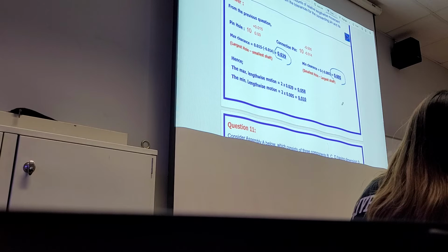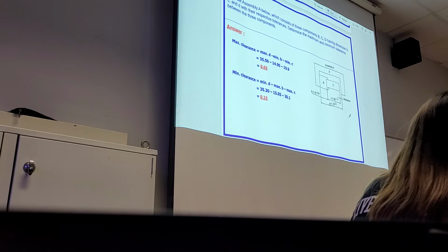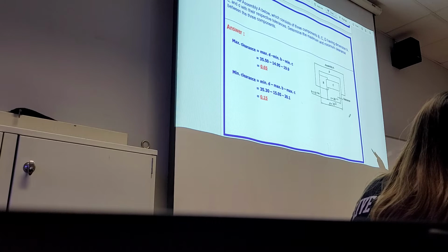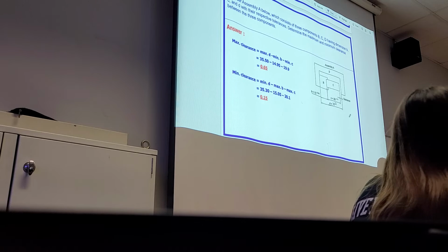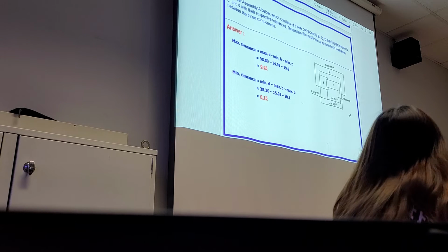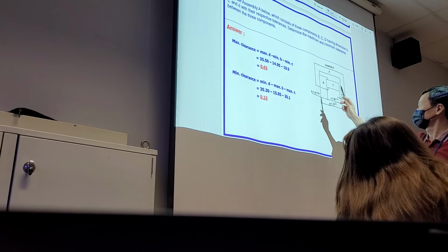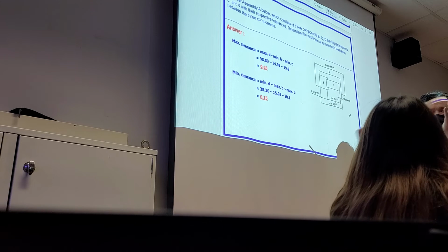Next, these are exactly the cases you are talking about. If I have a dimension accumulated like this, dimensions D, B and C, three dimensions, and there's a clearance here. How do I find the clearance for these three dimensions? With three pieces added together, the maximum clearance is when D is the maximum dimension, and B and C are the minimum dimensions. That's the maximum clearance.